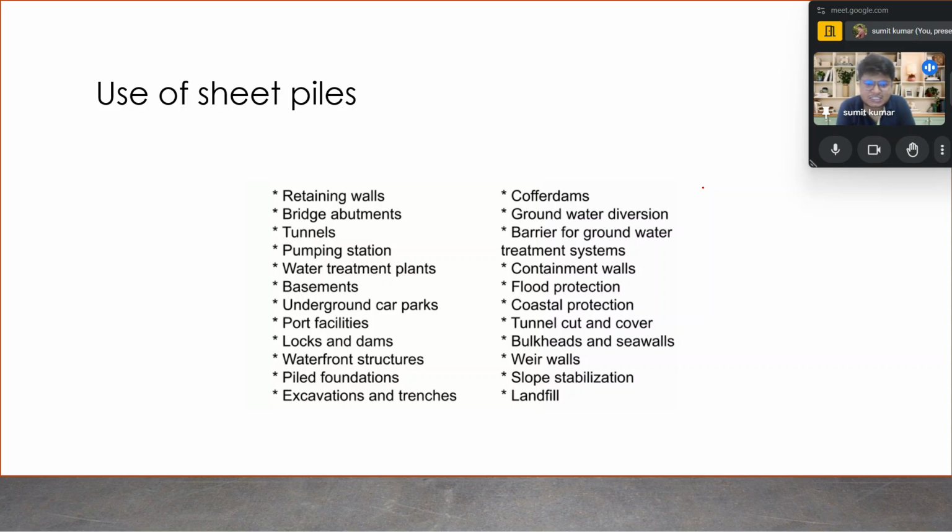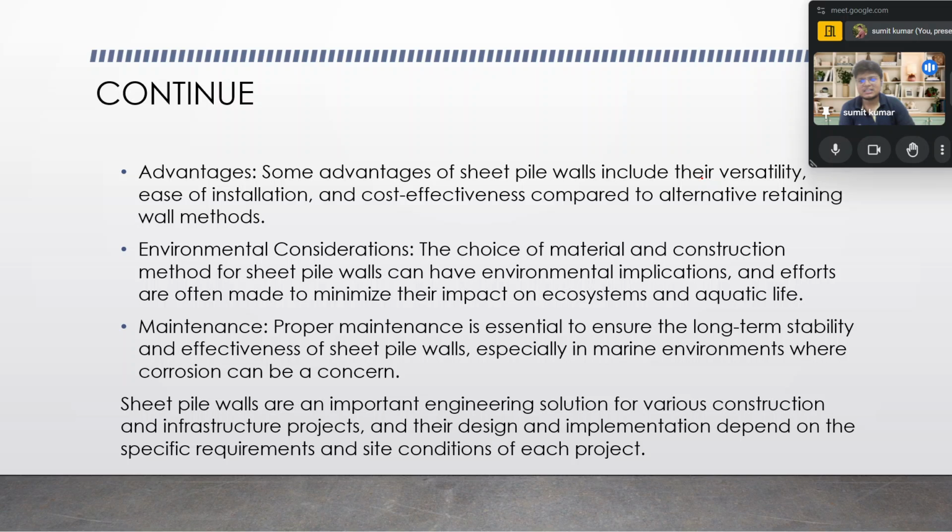Those are the temporary structures. Next one is the coffer dam, which we have come across. The groundwater diversion, barrier for the groundwater treatment system, containment, flood protection, coastal protection, tunnel cut and cover, bulkheads and sea walls, weir walls, slope stabilization, landfill. So there are various applications of the sheet piles, various usages of the sheet piles across many different conditions. Now we will move ahead and see what advantages it offers over the other